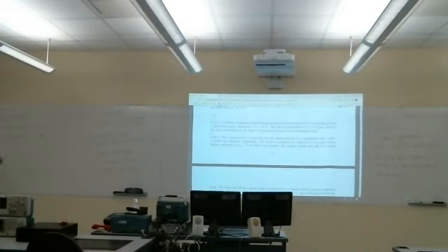At this distance, then, Zn of L, I'll write down the general equation: Z0 times (ZL plus J Z0 tangent of beta L) over (Z0 plus J ZL tangent of beta L).